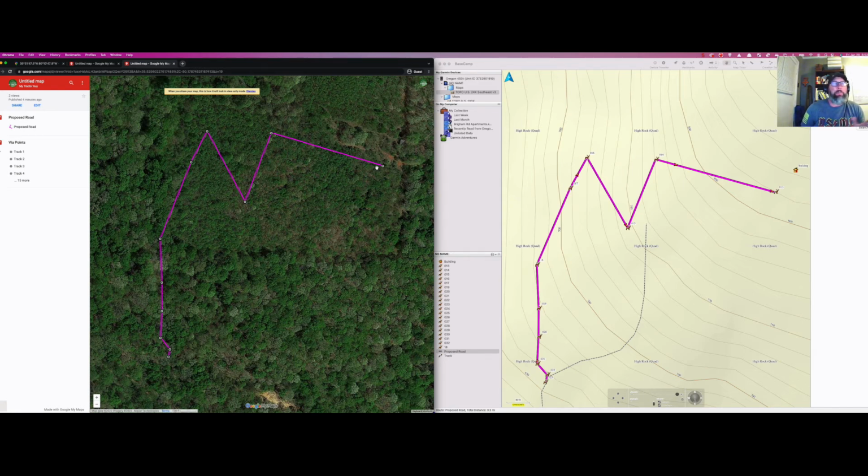And if it does, you can move to the left or right a little bit, provided that it keeps you in that same elevation gain to distance calculation. So you're dividing your elevation gain by the distance that you're traveling, and that gives you your percentage of slope. It's your rise over run. So how much are you rising in elevation compared to the total distance of your run going to the next waypoint? And when you calculate those out and you've got your elevation gains calculated, you can lay all this stuff out, and you would know,